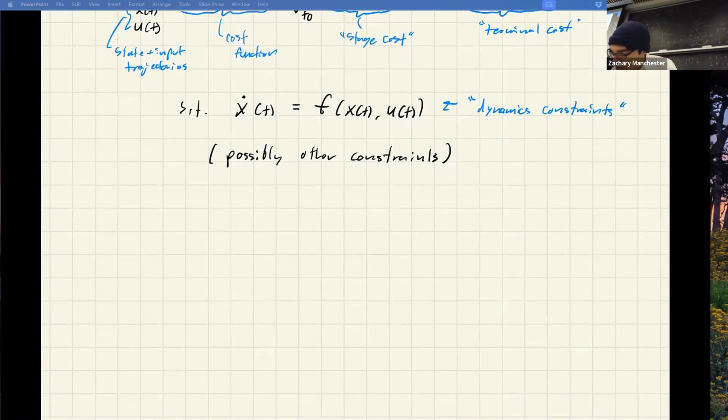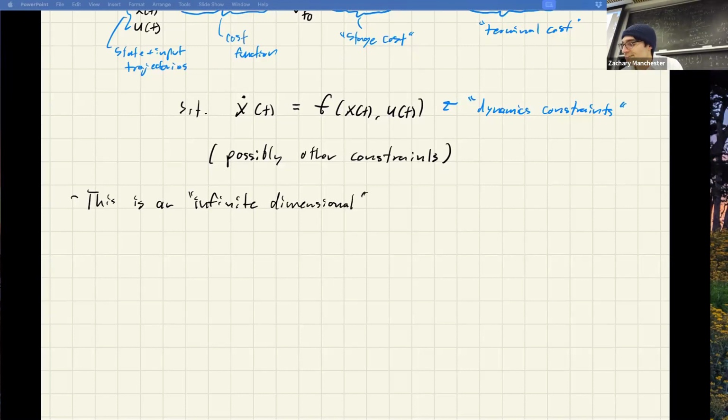Okay, cool. So the next thing to talk about is, write that down. What are the solutions to this problem? What do they look like? Anyone have any ideas? No? What am I solving for? Two trajectories, really, a state trajectory and a control trajectory. And the particular point I want to make here is the solutions to this problem are open loop trajectories. They're open loop state and control trajectories. I do not get a feedback policy when I solve this problem. That's the main point I want to make.